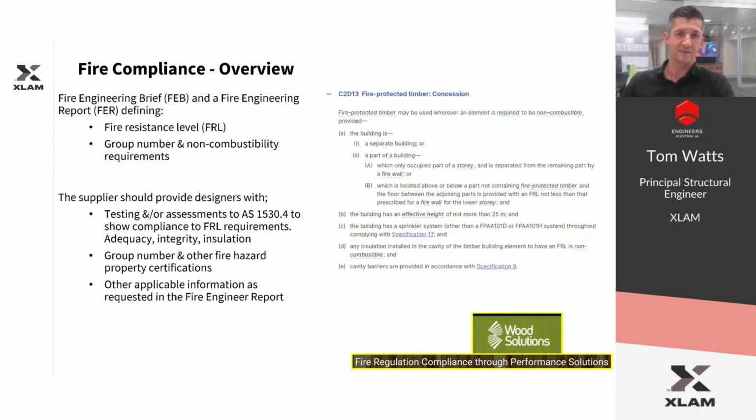In the NCC, there is a pathway for carrying out a fully DTS pathway for mass timber buildings. However, in our experience, it's actually quite rare, and I haven't seen a project that has gone fully down that pathway. There's normally one or more aspects which triggers the need to go to performance solution. It's not generally an issue. I guess the main value people often see in going the DTS pathway is it can be perceived to be a more straightforward pathway.